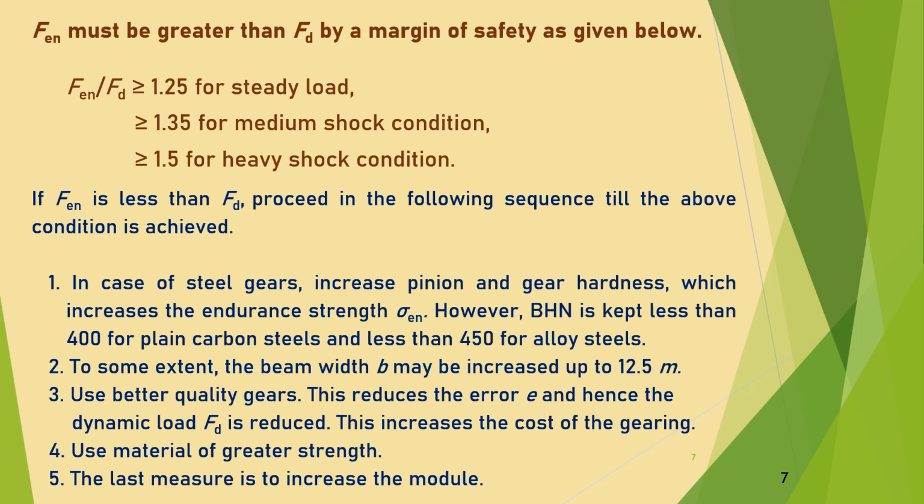This reduces the error e and hence the dynamic load is reduced. This increases the cost of the gearing. Use material of greater strength. The last measure is to increase the module.